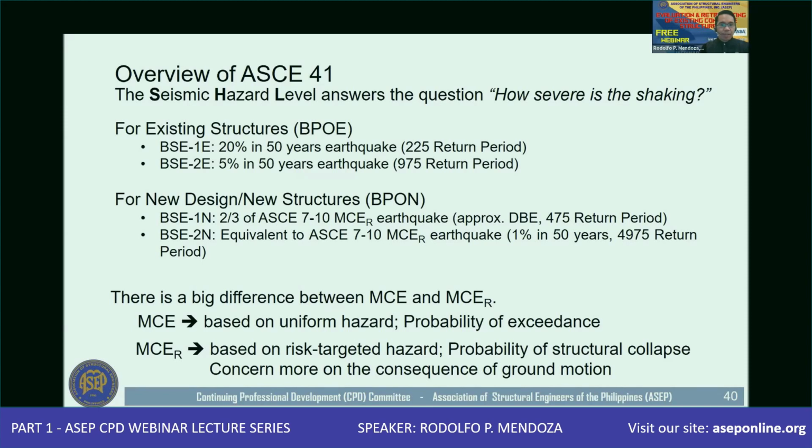Now, for new design, we have what we call BSE1N and BSE2N, representing the first one as DBE and the other one as MCE. It is important to note that there have been some changes in the definition of MCE for quite some time. Before, we just called it MCE, and now there is what we call MCER.